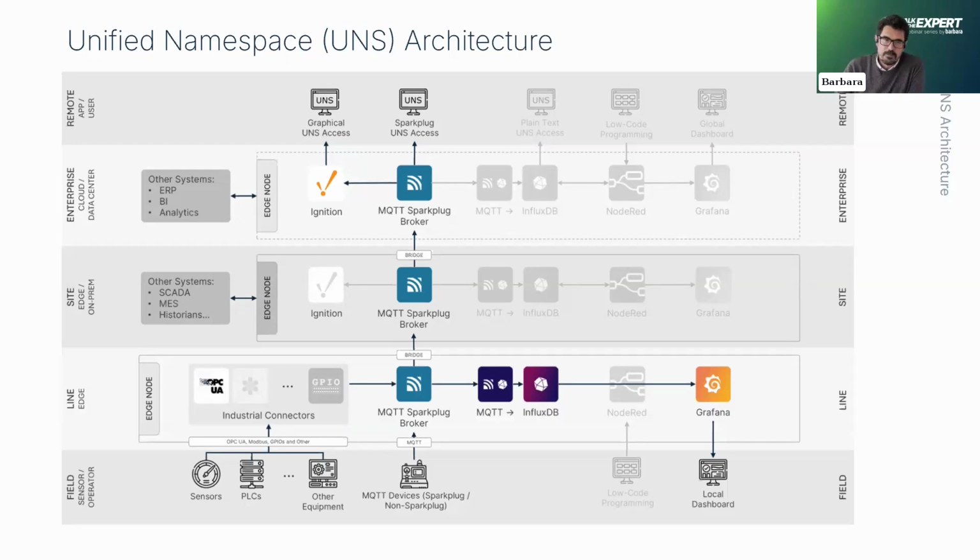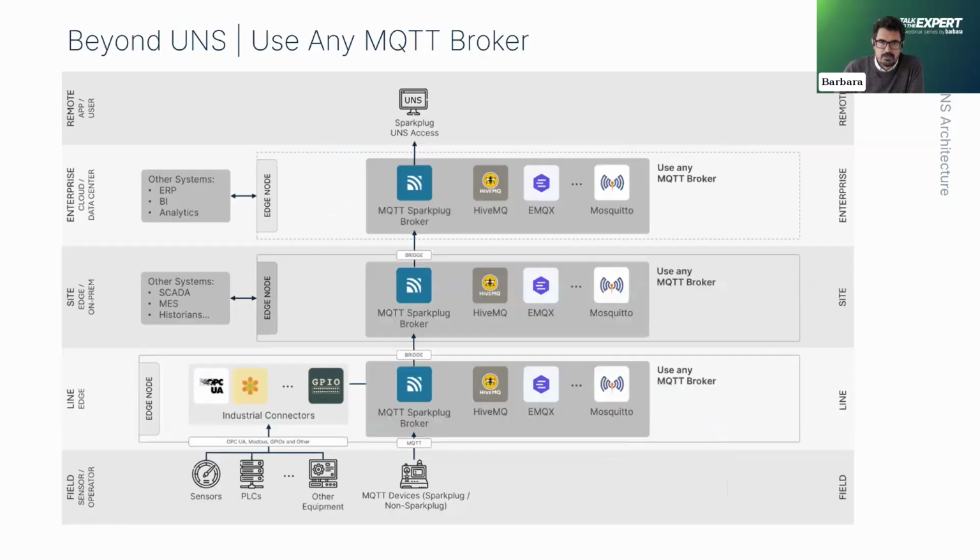Yes, of course. As we mentioned before, we need some kind of messaging solution to decouple these data sources and the data consumer, but we are not forced to use the Sparkplug solution. We have different solutions available in our marketplace. It is also very common to use HiveMQ. We can also use other solutions like EMQX or the generic Mosquitto applications. It is up to you to use the one that best fits your needs.